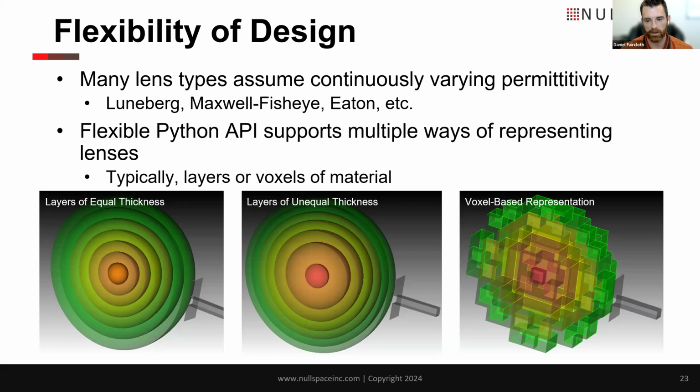And so with that voxel approach, that's already geometrically very compatible with the unit cell based approach that Fortify has for specifying permittivities and how that maps into those lattice structures. And so you can create the baseline voxel representation conformal to any geometry that suits your particular application, and then leverage Nullspace's accuracy and speed to optimize the idealized profile of that permittivity.